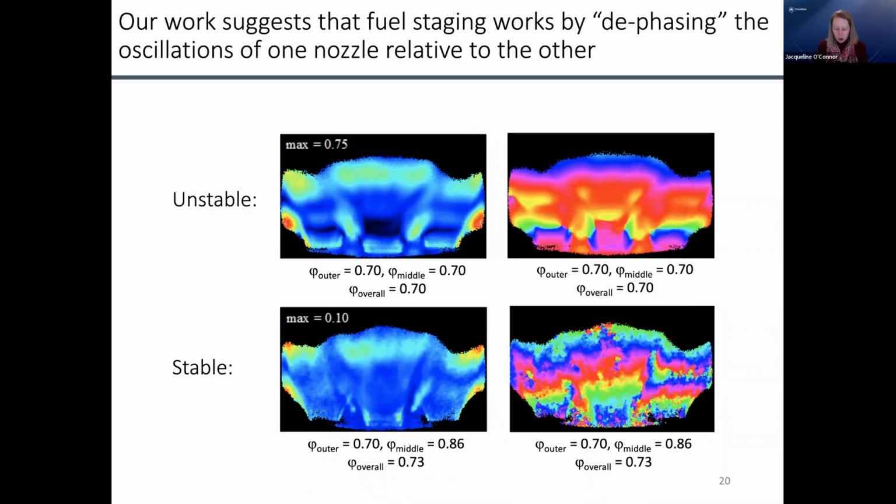Yeah, for sure. So yes, all of the above. For this particular experiment, our first cut is always the FFT, because if you have a really loud instability, all the interesting stuff is happening at known frequencies, right? Wavelets are really good in situations where you have intermittency, and some work that my student Ashwini Karmakar has done on the interaction between coherent motions and turbulent motions. She uses a lot of wavelets. We've done wavelet filtered POD.